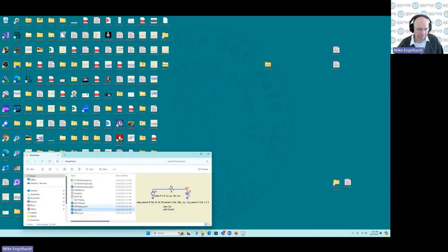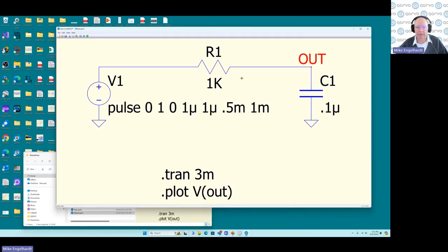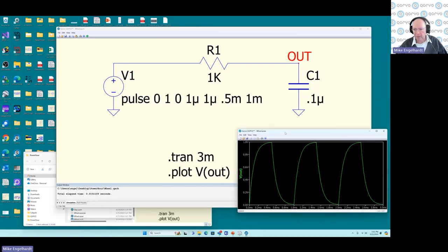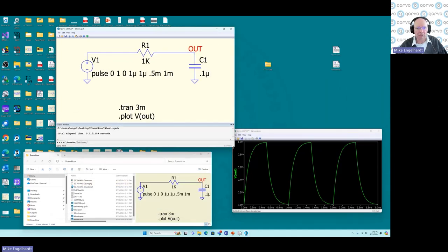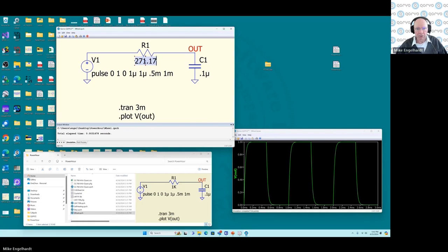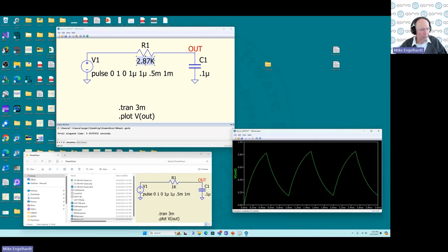The Alt mouse wheel thing. Let me show you what that does. Okay, so here we have again the Hello World SPICE simulation, square wave into an RC filter. But what you can do is adjust these values with the mouse wheel. So if I double click on this and hold down the Alt key and spin the mouse wheel, it changes and resimulates. And it's velocity dependent. So if you turn it very, very slowly, it's like pico part per million steps. And if you move it fast, it'll get away from you real quick.